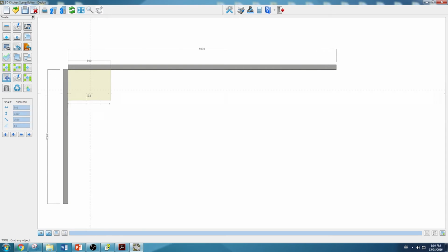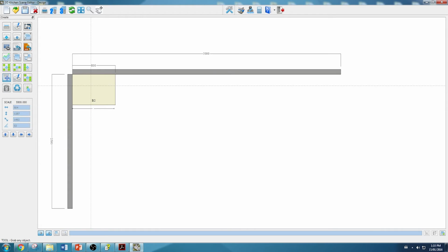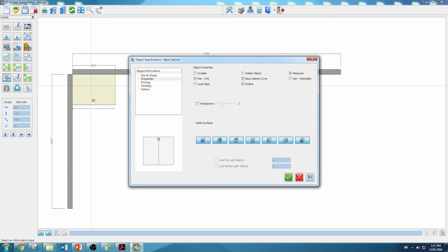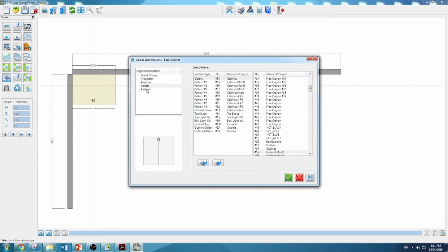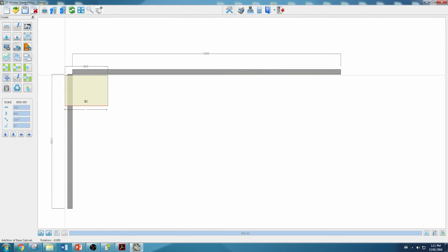Modify objects. Move the mouse pointer over the top of the objects you want to alter. If you need to get a difficult object, e.g. a small panel, move to it, then use the center mouse scroll button to zoom in or out into the object. Click the right mouse button. This brings up a new dialog on the screen, allowing you to alter everything about the object, such as size, shape, and properties.